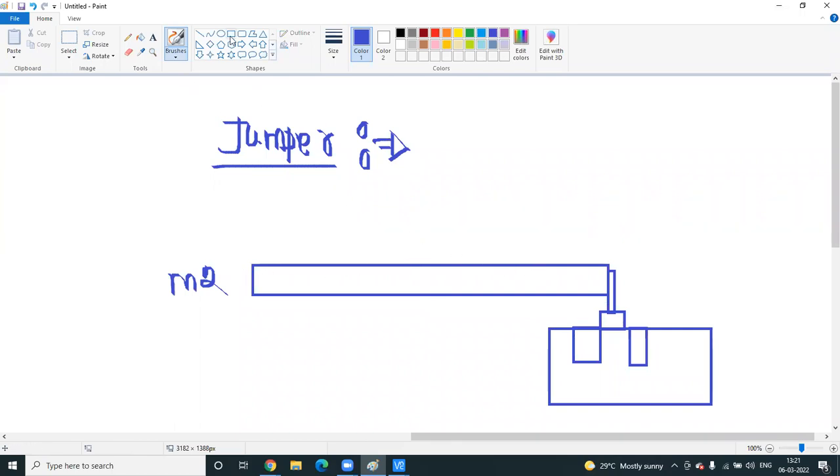So what are you jumping? As you understand, that is how the jumper works. You will chop this metal, then you will use a higher metal. This is the important point. Next, use the adjacent higher metal. Don't use M4, use M3 metal. Like your first floor is completed, you join the second floor. In the same layout also, you will use M3 metal, and it will be placed nearer to your device.